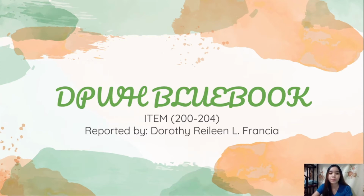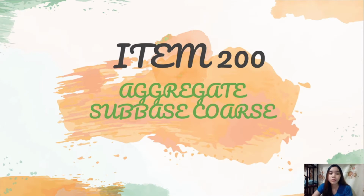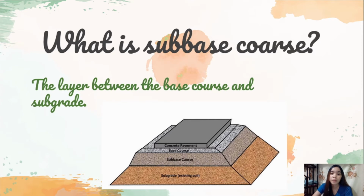So item 200 is about the aggregate sub-base course. First, what is sub-base course? It is the layer between the base course and the subgrade. It functions primarily as structural support, but it can also minimize the intrusion of fines from the subgrade into the pavement structure. Sub-base course also helps improve drainage. It consists of lower quality materials than the base course but better than the subgrade soils.